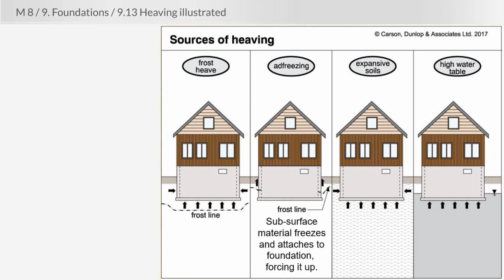Whenever we have expansive soils, again, clay, that can cause the ground to move up and down, especially every time the clay dries and then gets wet again. And whenever we have a home with a high water table, that can certainly cause the home to move around a little bit. We can try to control that high water table through the use of sump pumps and sump pits, but pumps can only do so much.